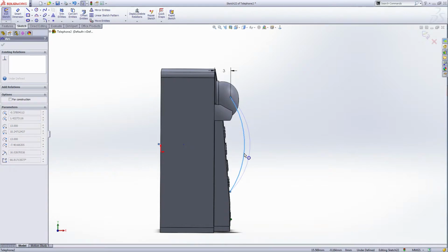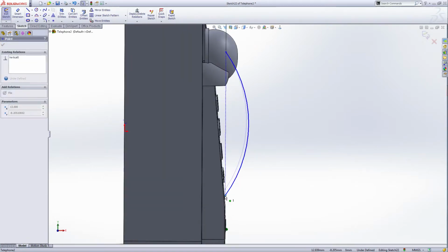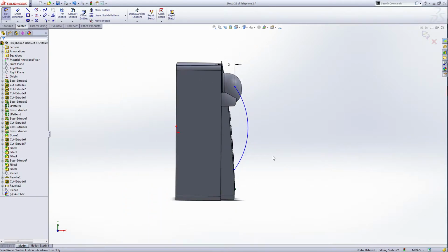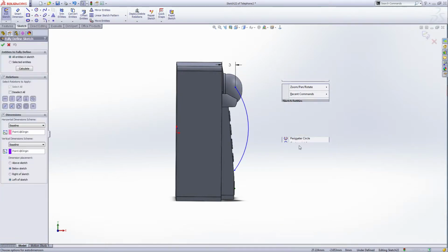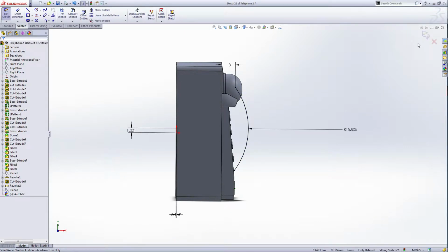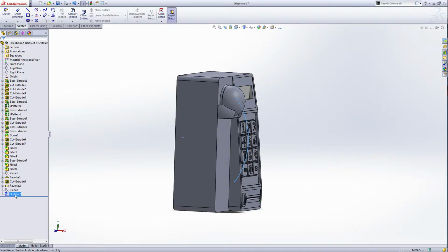Just this. Make it a little bit flat, not that. It's longer. Okay, so you can fully define this sketch if you like. Give it the position you like, and then fully define this sketch. You can check. Okay, now we exit the sketch. So we name this. Slowly double click twice. Name it path 1. Okay.